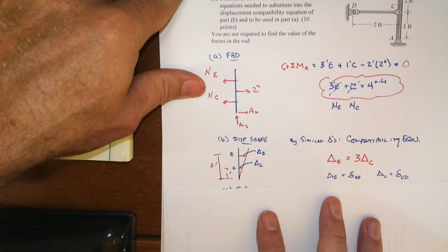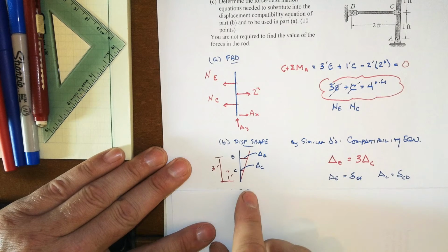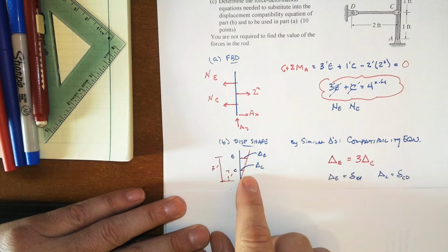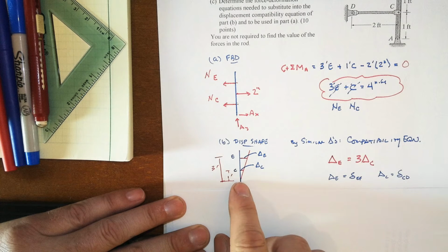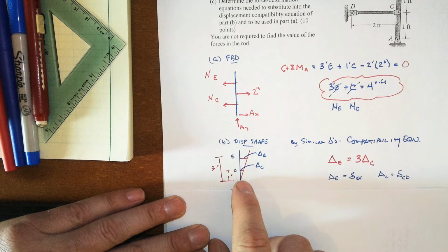The displaced shape that we're going to work with to get the compatibility equation that will make all this work is, again, to recognize the bar itself is rigid, and it will then rotate about the truly external point that does not translate. So you go to the pin at A. This is just like the examples. I mean, it is exact. Oh, well, hey, you put the bar vertical instead of horizontal. Well, who cares? What difference does that make? Well, gravity. But gravity's not included in the problem. So go with what we actually have in the model. That's part of the key.